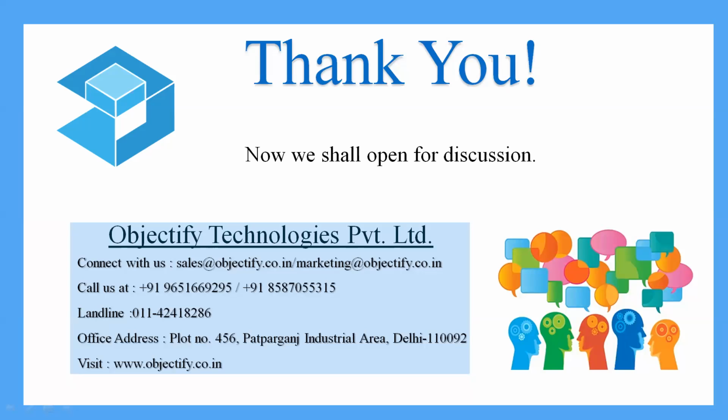So in case of CNC machine, if you are having a coordinated 3-axis machine or 5-axis machines, all those individual axes, if you are going to get the positional accuracy in the range of 25 micron for coarser machines, then your geometry accuracy that you print, that you process using CNC machines will be up to that.